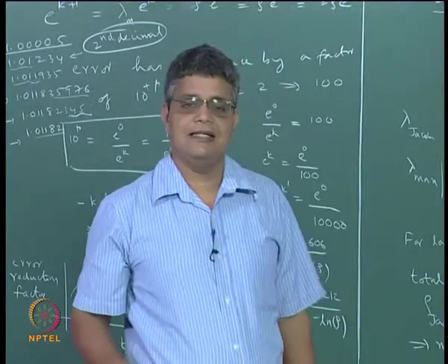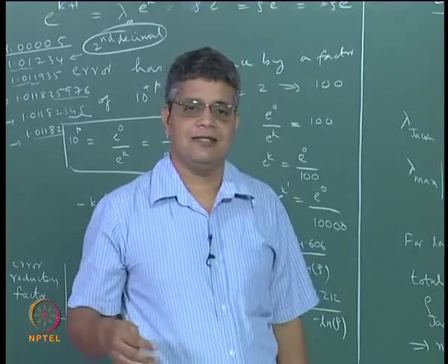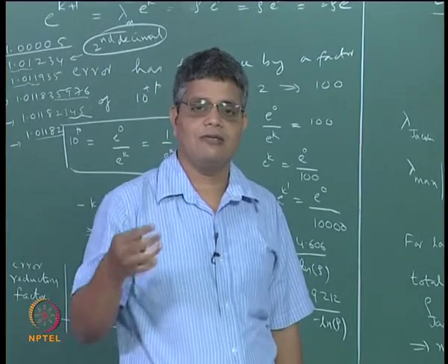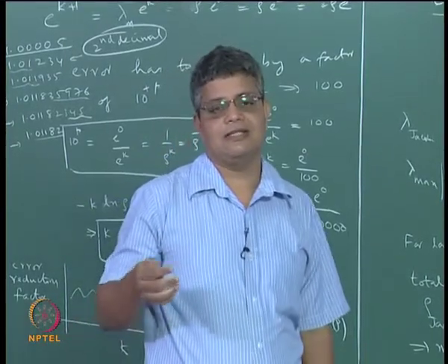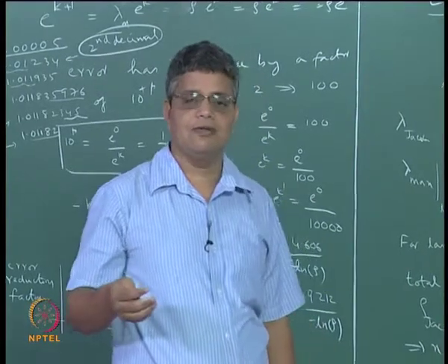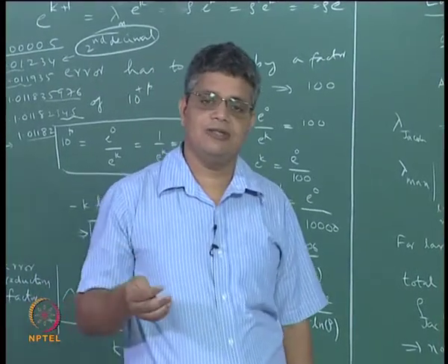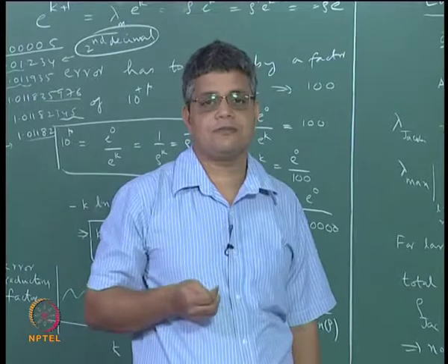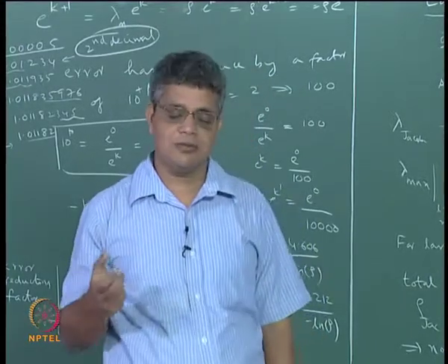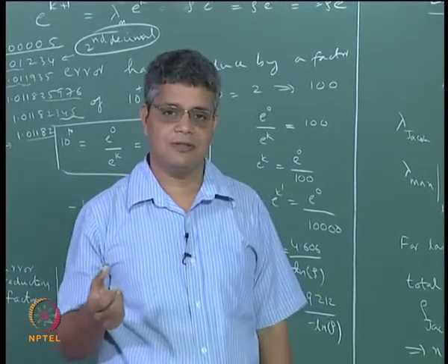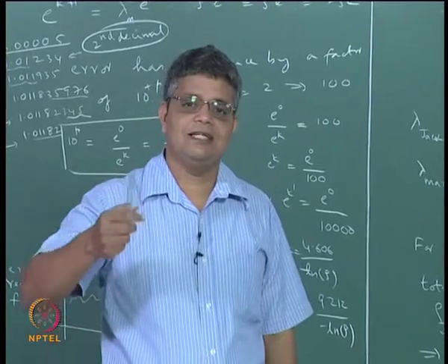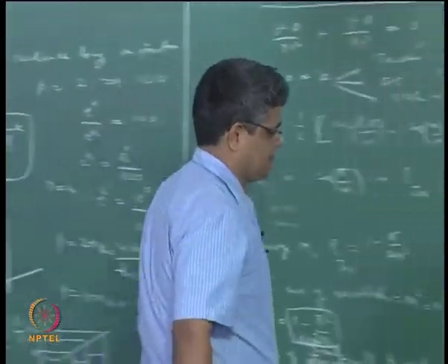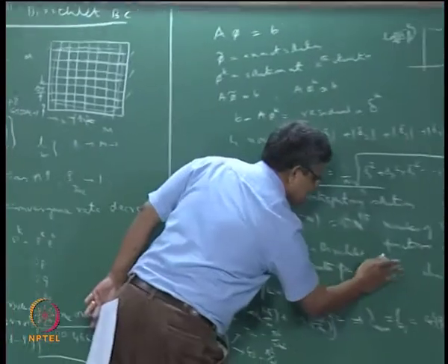In such a case the number of iterations required for one order of reduction of the residual varies as square root of n, whereas for Gauss-Seidel method and Jacobi method it varies as n. So the total number of mathematical operations required for convergence varies as n raised to power 1.5 instead of 2.